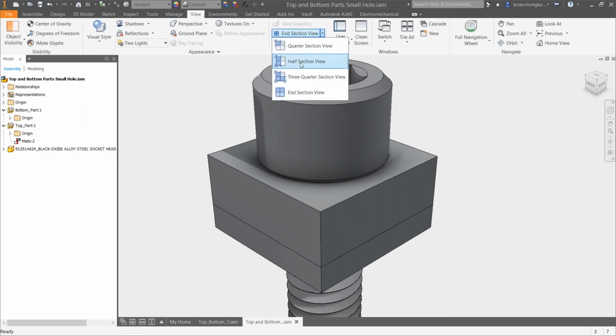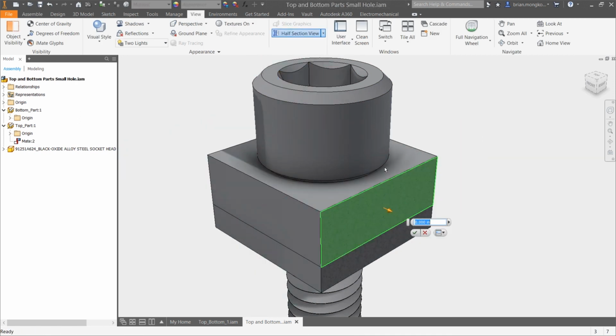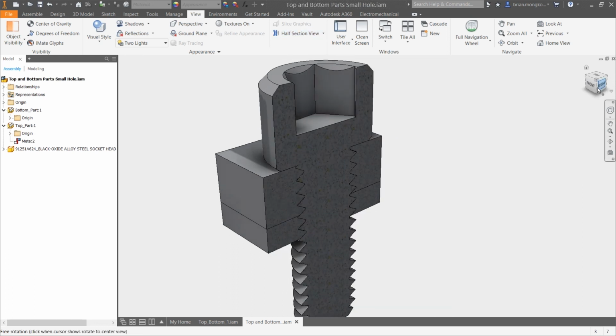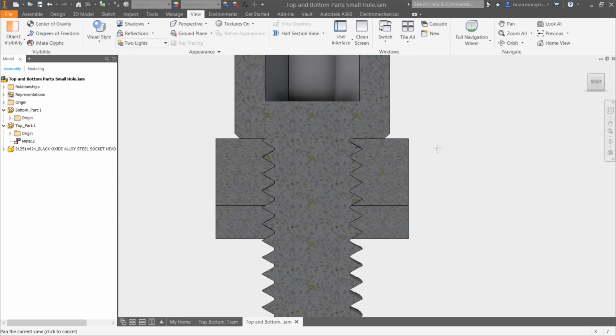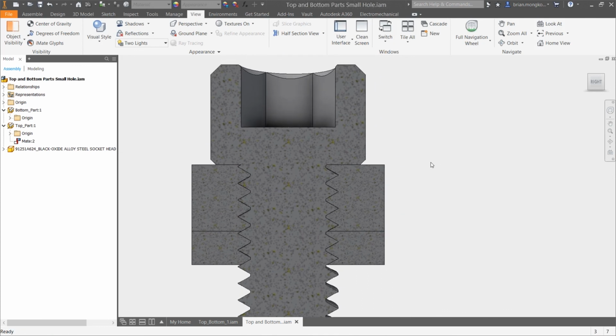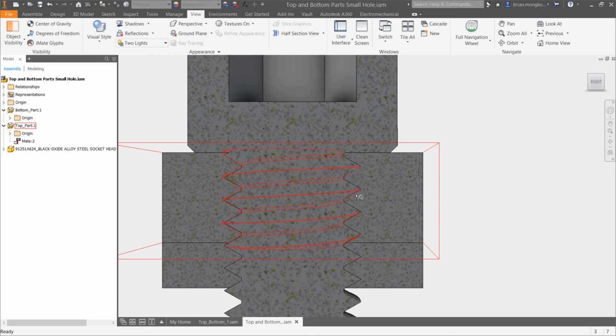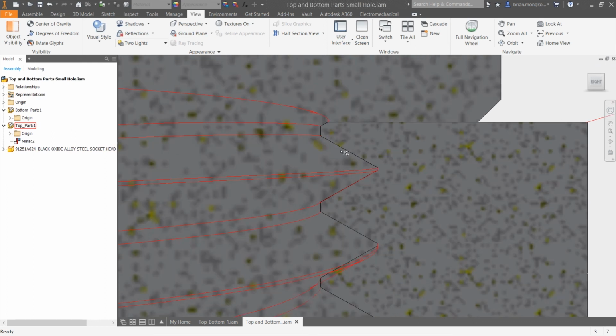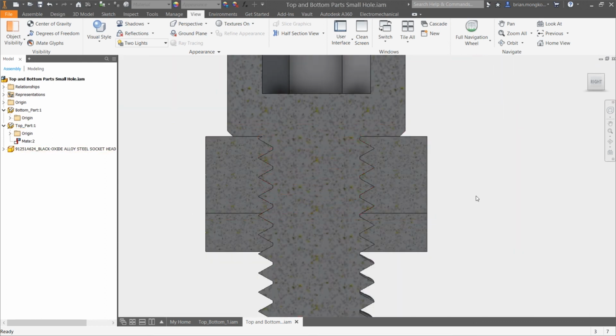I get a lot of questions like, hey, I want to cut this slot exactly as this other part is built. How do I do that without reverse modeling this thing? And generally these Boolean operations are what you want to be doing. And once you get that Boolean operation, notice how it didn't give me that offset, that tolerance that I'm looking for, but it did give us once again a snug fit to the body.